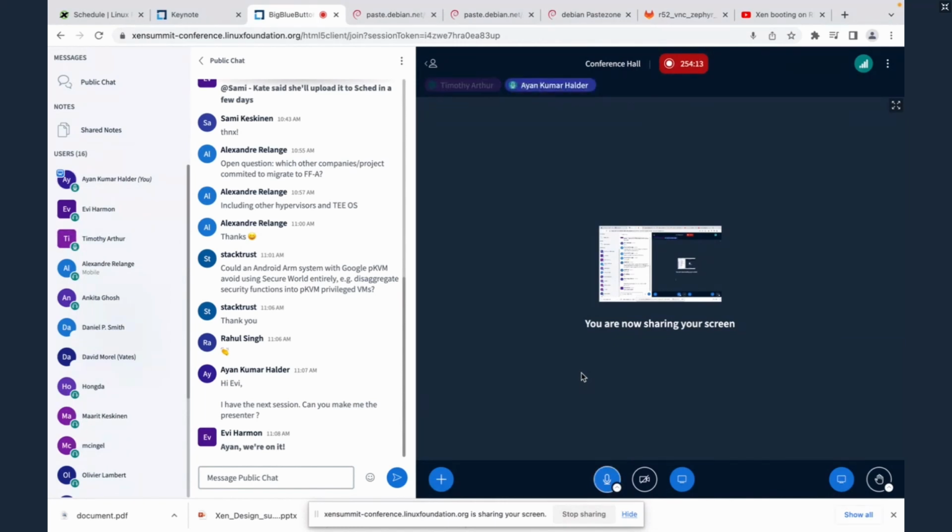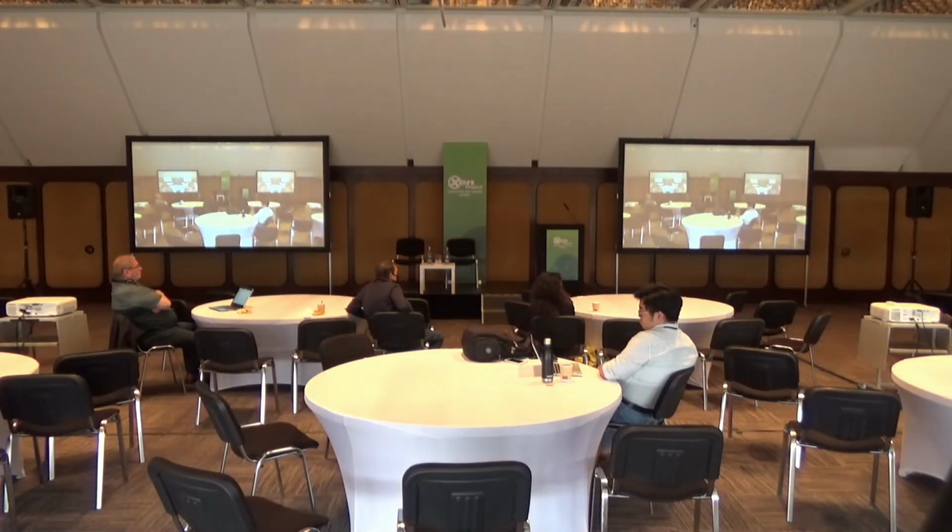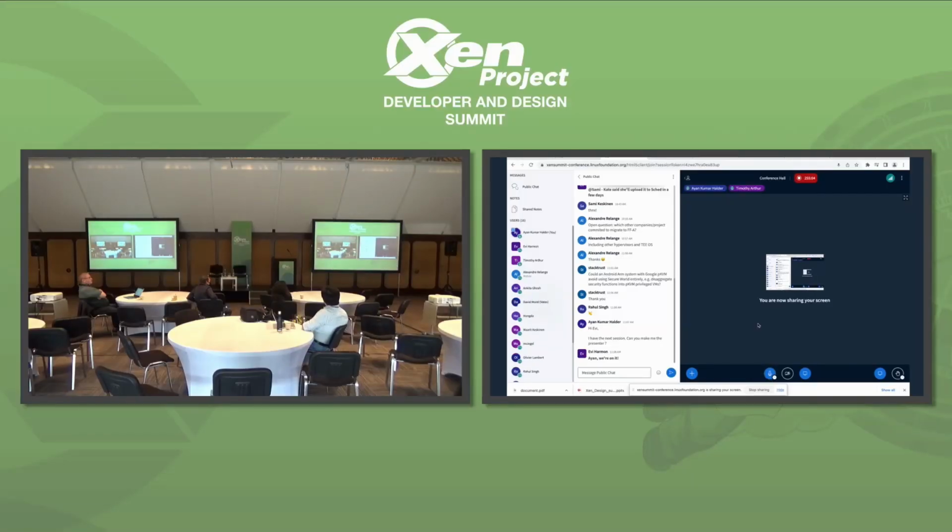Yeah, sure. So we use these timers just to show that the guests are able to configure the MMIO, and we are able to get the interrupts. So we could have used any other MMIO devices to showcase that the guests are able to run their interrupt handlers. So we used TTC devices here because TTC devices were available. There were 4 TTC devices available on the platform, but internally the guests are using the ARM v8 timers. These TTC are MMIO devices. You can take any, like SPI or UART, those kinds of devices. So we wanted to basically show that the interrupts are getting generated from the MMIO devices which are passed through to the guest. Does it make sense? Yeah, it does. Thank you.